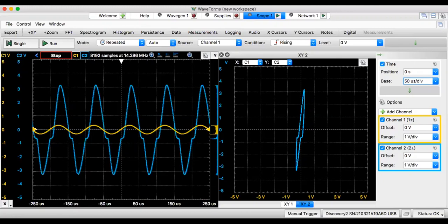That's not a problem because the signal right now is 10K, 10,000 hertz. So 10,000 hertz is no problem because the bandwidth is 13,000. So now we have a 10,000 hertz input signal, no problem. The gain is still 11. Look at here.